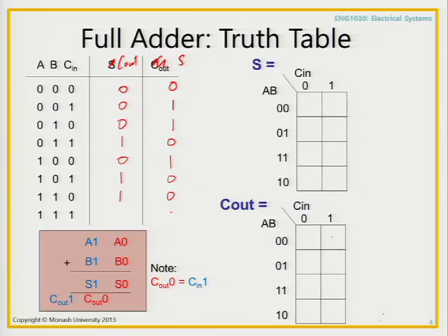Well, 0 or 1? 1, okay, because we've got 3 bits. You've got 1 on the sum and 1 on the carry out. And what does 1, 1 represent in binary? 3, right? Okay, so that's awesome. You have now specified your truth table from a described behavior.